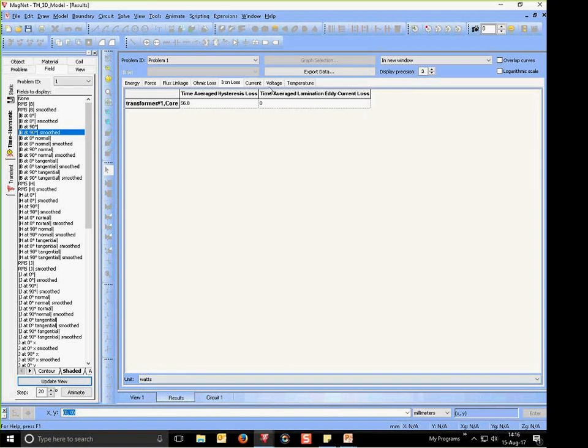As I said before, because our fitting coefficient was about 0, we could not generate any eddy current results. So depending on the data that you give to the software, it will estimate your losses depending on that data. This implies that when you are defining your materials, it's very critical to consider the point of operation of your material and the data that you are using.